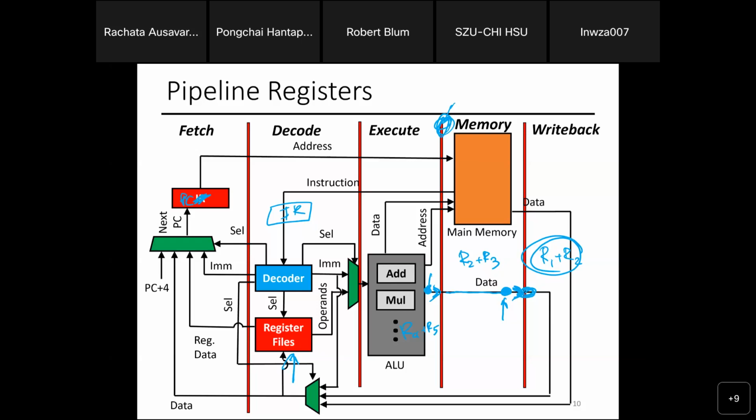So the quick answer is, if you do not have the clock, this whole design can handle one set of input. The whole output will be just based on that one set of input. And in order to feed the next input, you need to separate the two inputs in sequence, in time. The way we do this in digital design is to clock them, because each cycle specifies one step in time, so you can organize the input flow that comes in and expect the output flow that would come out of your design in a sequential pattern.